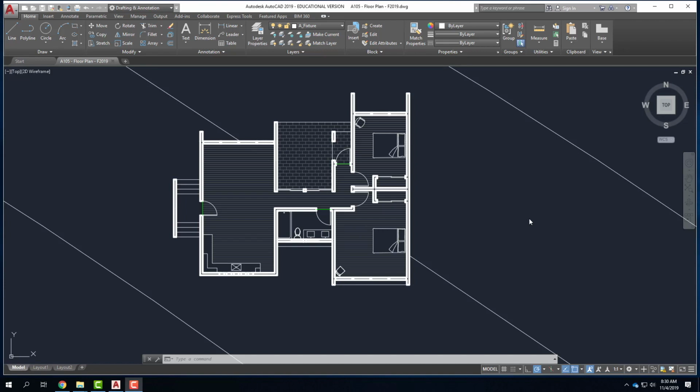Furthermore, there's complexity to a roof. Where does it fall? Where do various pieces of the roof hit one another, etc.? Frequently, it's easier to resolve this in 3D, pull up SketchUp, pull up Rhino, figure out where the roof goes, and then come back and draw it from there. But for our purposes, we're going to try to figure it out in the elevation view.